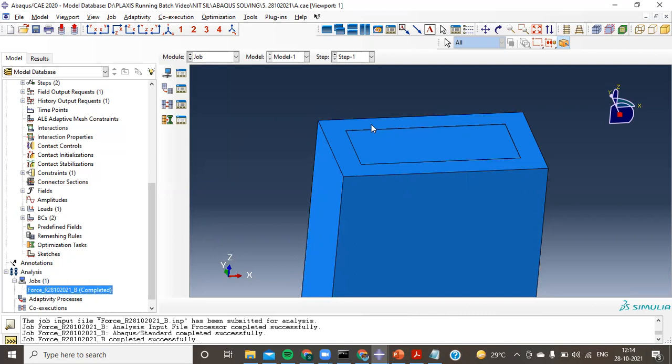I'm trying to distribute an equal amount of load on the carbon fiber and on the steel, whereas steel won't bend that easily, but the carbon fiber will bend very quickly. But the steel component and the carbon fiber are tied to each other, so when one is trying to bend very quickly and the other is not, there is a mismatch between these two. That's where it is causing an instability in my solution. That's the statement you need to give for that particular warning message.